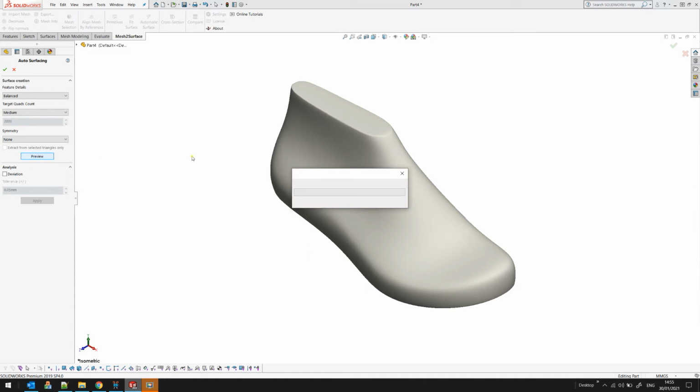You just press preview to see what the result will look like. It takes a while on different objects because the algorithm analyzes the underlying surface. I would like to say that all the meshes must be closed, manifold, not have holes, in order to get a good result.